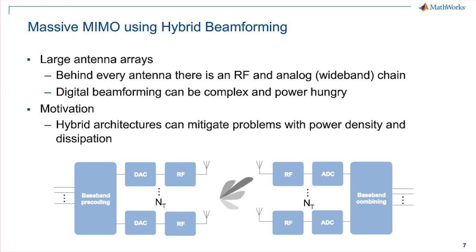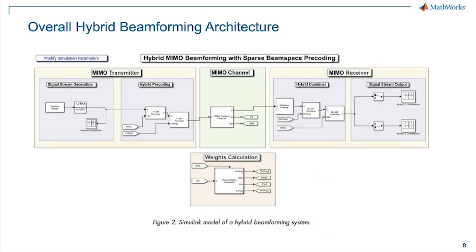And that is the reason why we're talking about hybrid beamforming as a compromise between performance, complexity and power usage. What I'm showing you is essentially one way of describing the overall hybrid beamforming architecture, where you have baseband signals generated at the gNodeB or UE, and we have the partitioning of the MIMO transmission scheme into digital and RF beamforming or MIMO.